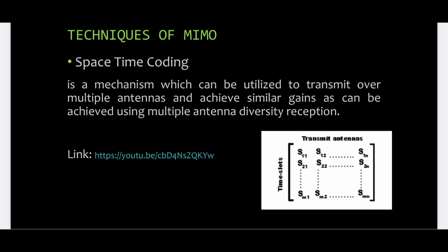Space-time coding gives the vehicle a way to transmit on all 4 antennas and achieve a similar gain when the handheld is limited to a single receive antenna, thus making the link symmetrical and much more useful for bidirectional communication.